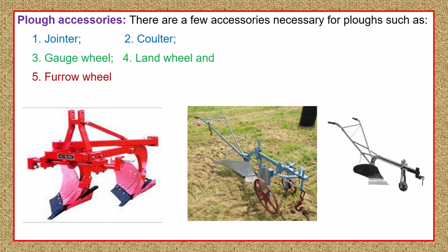In such cases, having a miniature plough as a jointer will remove the small ribbon-like furrow soil mass in front of the main plough bottom and leave the land cleared for it. That's how the main plough bottom goes deeper in the soil and performs to its maximum potential.